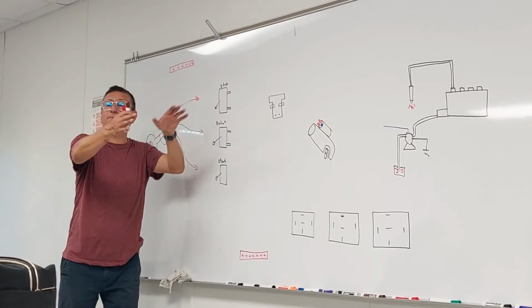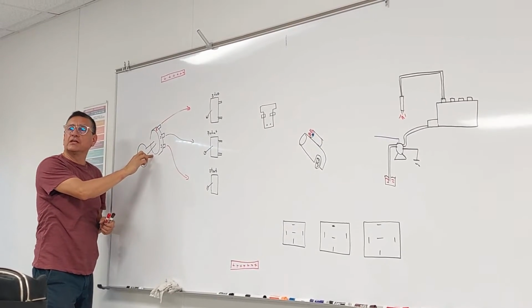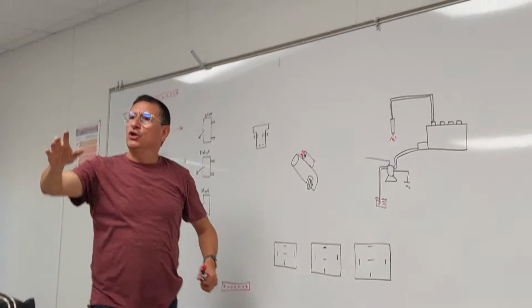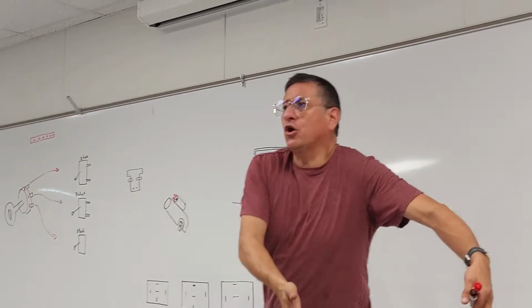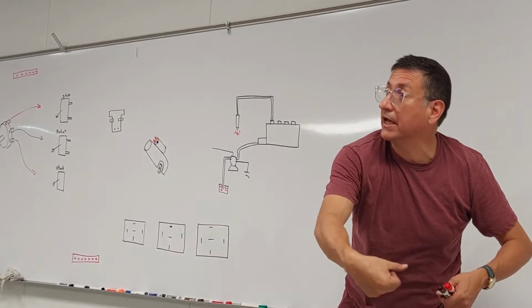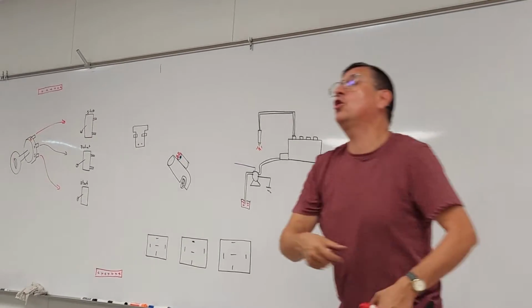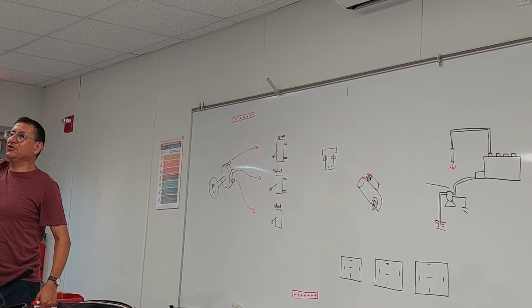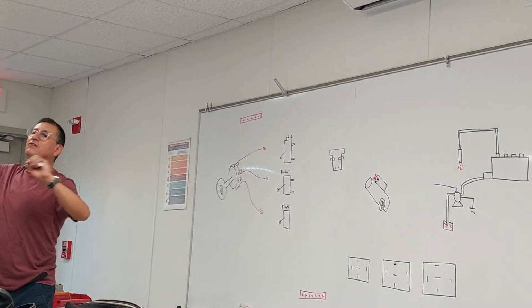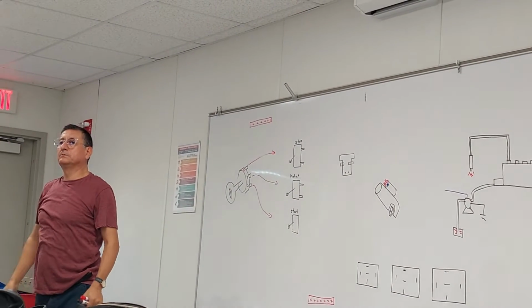At the end of the diagram, we are going to eliminate that one and we are going to connect the switch. In other words, you have a generator or engine here in the engine room with the control box, and you can start the engine here in the engine room directly on the switches. Or you can start the engine in the pilot hand with the ignition switch. You can connect both of them in parallel.